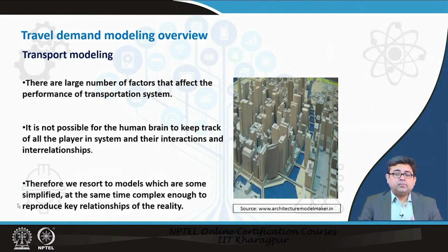If you combine these 4 aspects of the need to travel, you would be able to determine at a macro level what the demand for transportation in your city is, and based on the demand you can then provide for the capacity, such as the number of lanes in a road, the number of bus routes in a city, or the frequency of your metro rail, and so on and so forth. That is essentially what we would want you to be aware of when we are talking about transportation modeling.